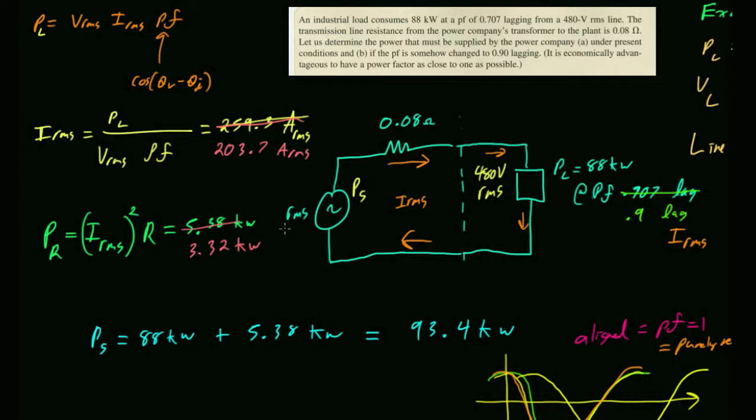The users are still using the same amount of power. They're still receiving the same amount of power, but just by changing the phasing of their load, it's actually causing less power to be burned in the resistor, in the line. It's more efficient, so everybody saves money, right? Either they're going to pay less for their power, or the power company's going to waste less. It's a win.